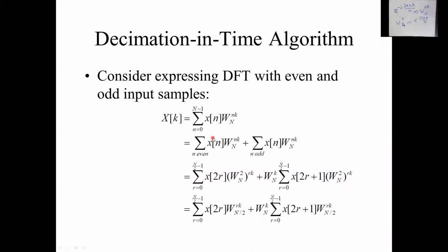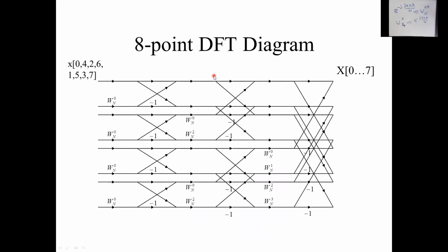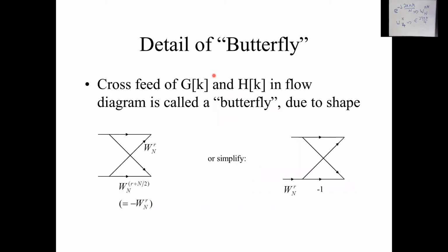So you can simply write this butterfly model to represent whatever multiplication you want between each two terms. Accordingly, you can expand this for 8-point FFT, for 16, 32, 128, 256, 512 FFT using this model. It's the same model, my dear students.